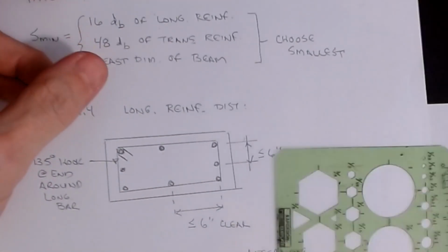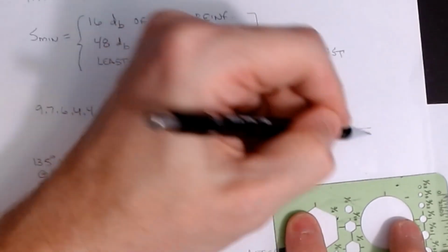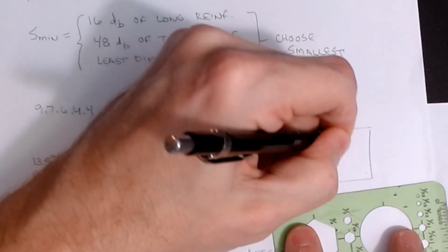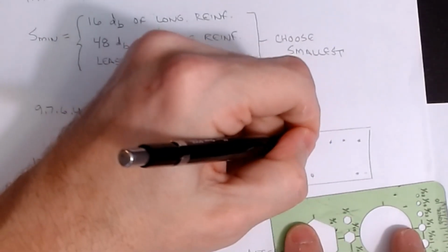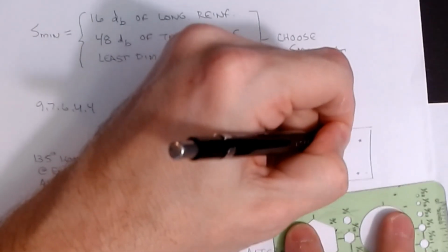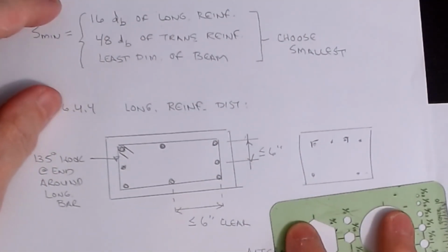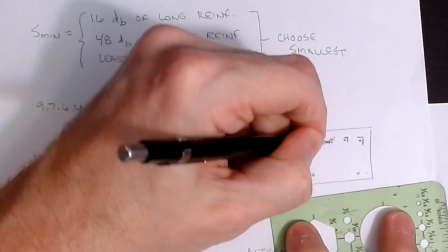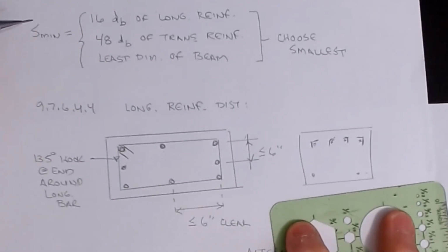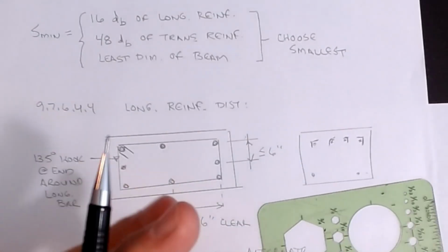So if I have, say, a section where I've laid out the steel for torsion such that it has 4 bars, like this, I would have to have a corner here, and the requirement says I would have to have a reentrant corner there to meet that criteria, right? And at the outer corners of this, clearly I've got to have a corner here, which means now I need one here. See how we've kind of chosen how those are being laid out?